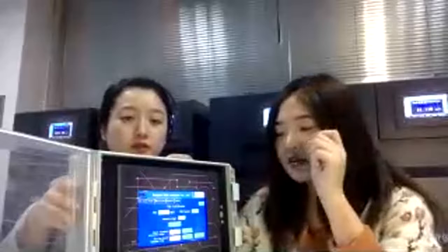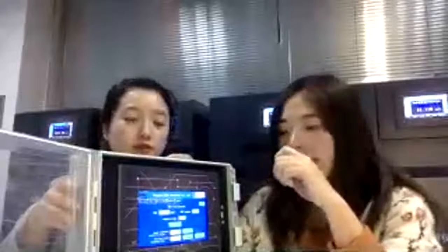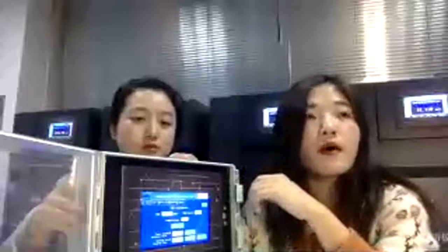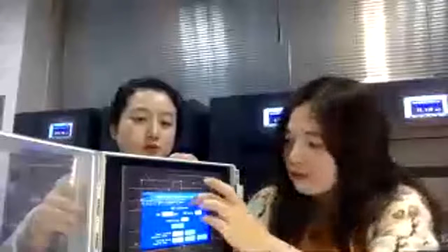That means in the real testing site, you can set how many minutes or how many hours between cleanings of the sensor. This way the TSS sensor can have a longer lifetime, and the data will also be more accurate.